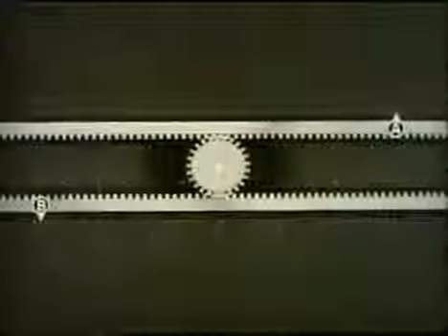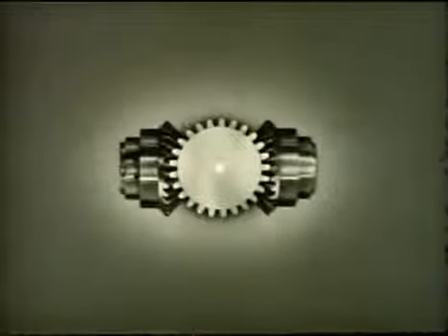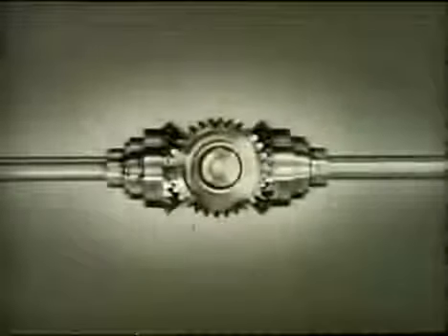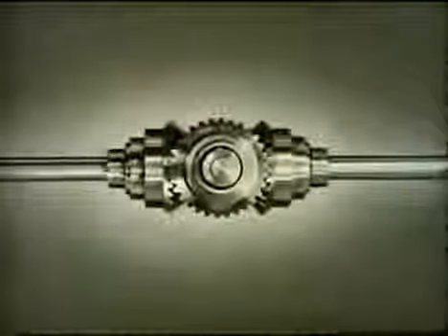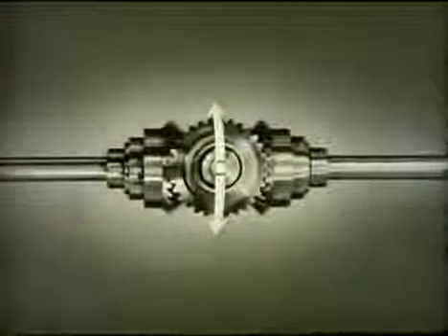There is no fundamental difference between the rack and pinion differential and the bevel gear type. The racks, which are limited in length, are replaced by end gears, which serve as endless racks and handle values in the same manner as do shafts. The pinion is replaced by the spider gear. Movement of the spider gear center along its circular path is delivered as rotation of the spider shaft.